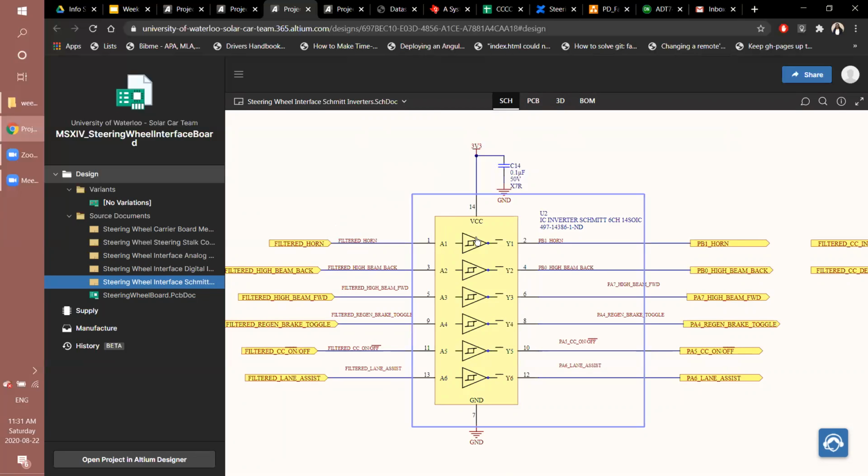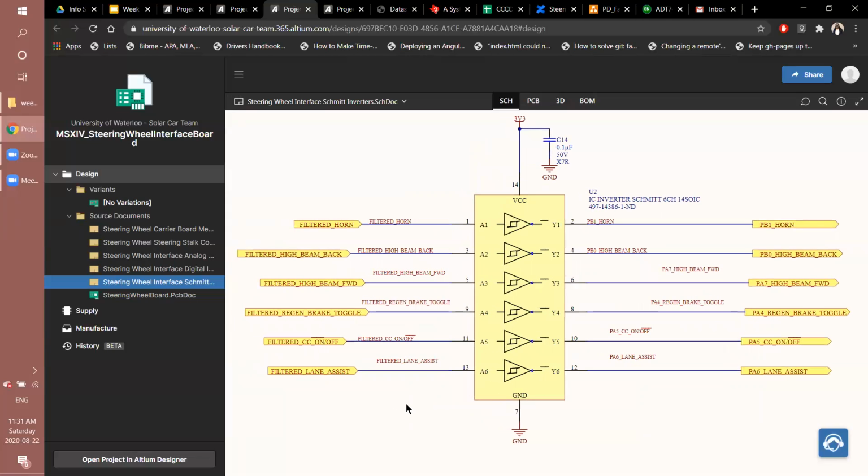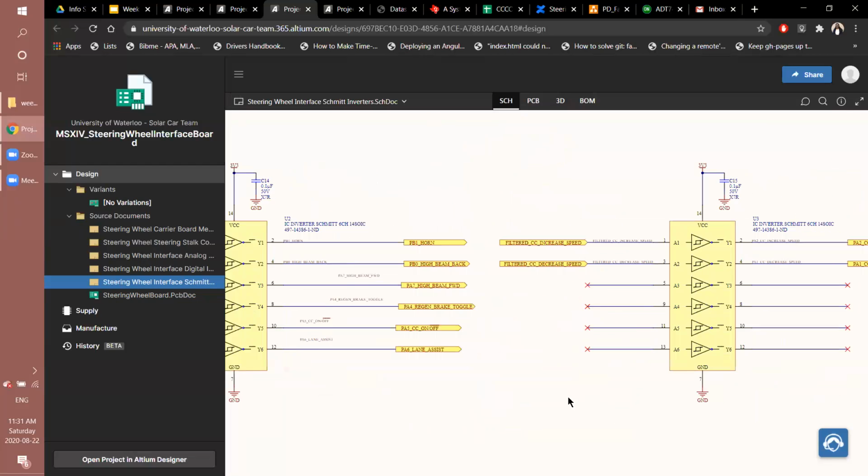So as a trigger, it latches the digital outputs until you clearly are executing a low versus high on the inputs. This is pretty useful for us as part of the filtration for both the noise sources on our digital lines and our debouncing. And so that's why you see it for all of the button inputs.